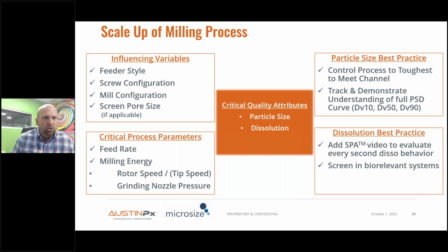And with both of those, we can evaluate vibratory feeders, screw feeders, either single screw or dual screw, volumetric feeding versus gravimetric feeding. So all of those configurations are possible. Decide on which one is best for that particular DPI, hold that constant, and then explore the feed rate lows and highs that are possible throughout development.